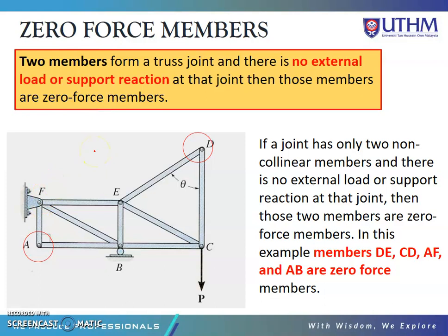So this condition is fulfilled at point D, which has two members and doesn't have any external load or support, and also at point A, two members. At point A there is no external load and no support reaction. So this and this will become zero force members.